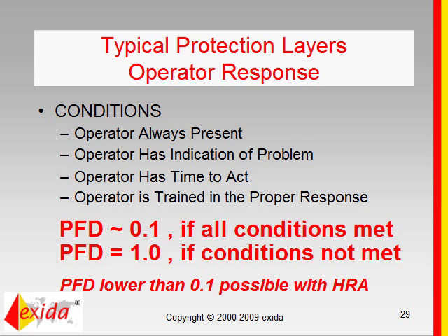But also keep in mind that many of the people involved in these types of analyses, the layer of protection analysis or the PHAs, sometimes do not include the actual operator, maybe a supervisor who says, well, we have an operator for that. But if you talk to the actual operator, he may say, well, it's probably better not to count on me because I have all these tasks to do, and I may be on my round, and I need to react within 30 minutes, but my round is an hour. That is something to take into consideration as well.